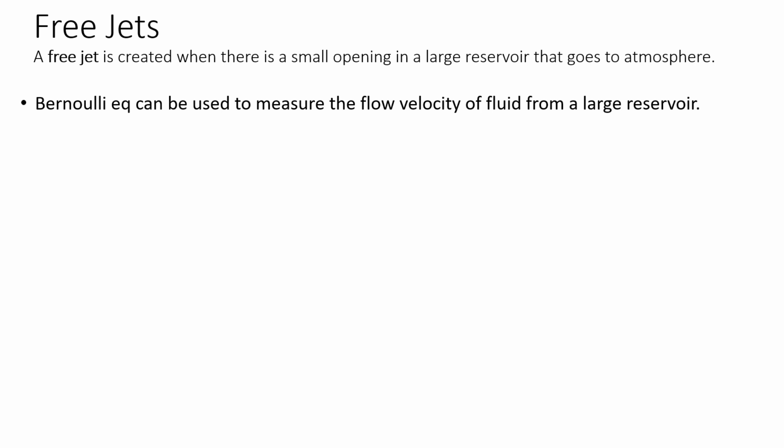Now we are going to see some applications of the Bernoulli equation, and the first application is measuring the velocity of a free jet. So what is a free jet? A free jet is created when there is a small opening in a large reservoir that goes to the atmosphere. It means that if we have a large reservoir and there is a small opening at the bottom here,